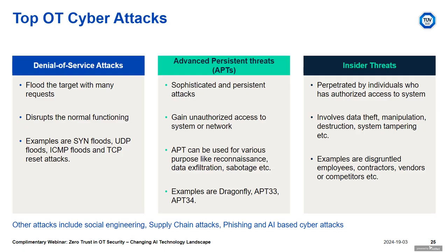These target network infrastructure, so they are specific to control systems. Generally, the mitigation strategies for this are IDS and IPS solutions. You keep monitoring your network to understand if any DDoS or DoS attack is being performed. Even a small pinging attack comes into the DDoS category, considering you are halting the network or consuming the bandwidth to make the system unresponsive.